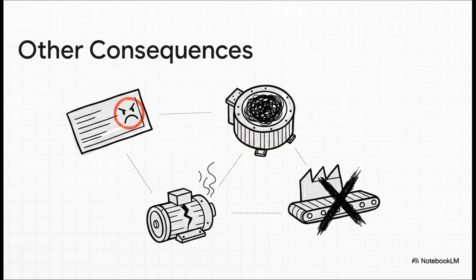It's crazy. And believe me, the damage doesn't stop there. On top of everything else, your utility is probably hitting you with direct penalties and those high demand charges. You're wasting precious capacity on your existing transformers, which might force you into an expensive upgrade you don't even need. That extra heat, it's slowly killing your equipment, shortening its lifespan. And the voltage drops it causes can trip sensitive systems, leading to really costly downtime.